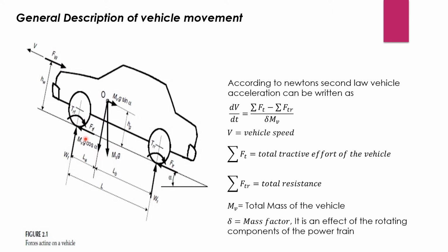The tractive effort Ft in the contact area between the tires of the driven wheels and the road surface propels the vehicle forward. It is produced by the power plant torque and is transferred through the transmission and final drive to the drive wheels.